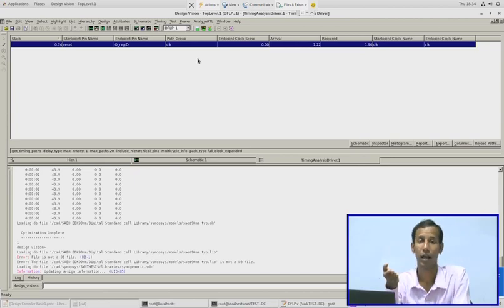The definition of slack is the required time minus the arrival time. If the required time is more than the arrival time, it is okay. But if the arrival time is more than the required time, you will get negative slack. Negative slack is not at all practicable. For a practical solution, negative slack will be avoided. You need the slack to be 0 or near 0, in the positive domain.